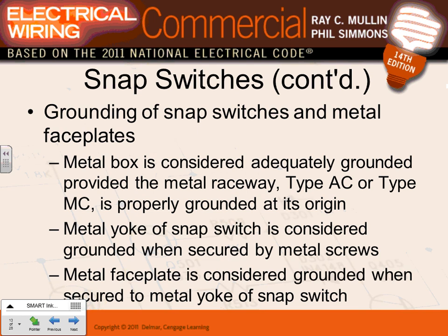The box, the housing of the receptacle, has to be grounded. The frame of the receptacle has to be grounded. The box of the switch has to be grounded. The frame of the switch has to be grounded. Same thing for the receptacle, by the way. And the cover, if it's metallic, has to be grounded.